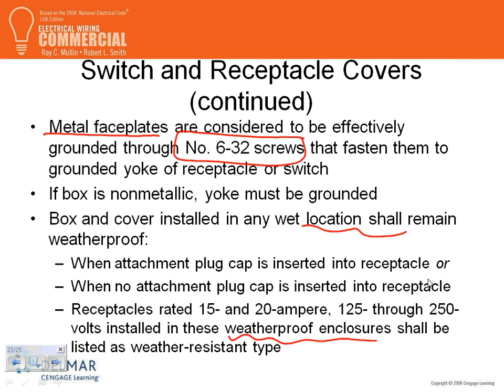Weather resistant, I can't emphasize this enough. Not only the receptacles that you put outside in wet and damp locations, but they are going to be a special type of receptacle. If they're that type of receptacle, guys, most of the time they are weatherproof, but you have to make sure it has the WP on it. Even outside the residential, they added it to the residential. In a commercial building, an outside receptacle in a wet or damp location has to have the WP on it. Weatherproof.